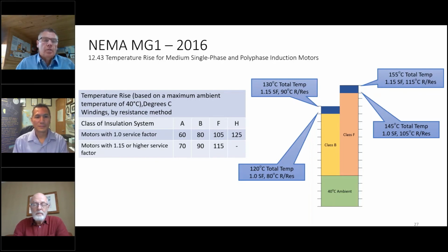So with motors in general, let's just use the NEMA world, the T-frame world, the 449 and down, there's quite a lot of margin put into those and a number of assumptions, like the type of wire. And part of getting your CSA certification is to prove the design as well.